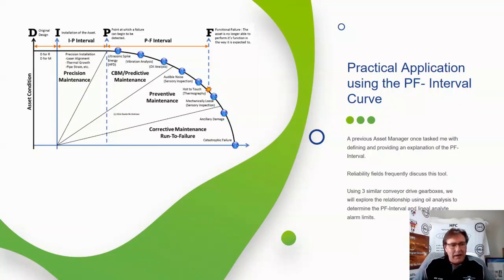My particular background is in oil analysis, and I believe that with a chemical signature, you have the ability to make that change before it becomes a permanent fault frequency. Others might disagree with that, and that's fine. We all have our strengths in our different CM-based technologies, right? So I looked at basing my assumptions on conveyor drive gearboxes and feeder drive gearboxes, and how we could go about tracking and trending those analytes, to reduce those failures or eliminate them and get them down to design life.